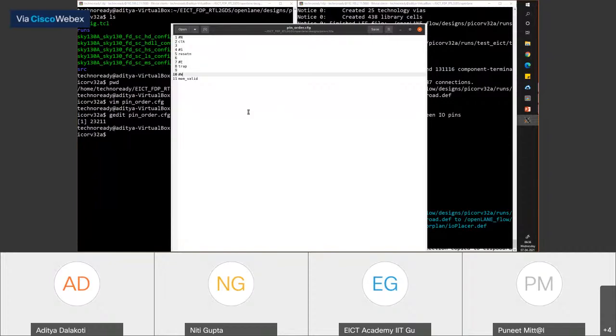Yes, basically I'll show you what north, south, east, west meant with respect to the chip. These are terminologies which are forced by the tool; the tool only understands these names. Also, to add to Naveen's question, how do you decide pin directions? It's also the external routing ease and the internal routing ease of your design. Based on how you place different pins, the routing may be difficult or easier.